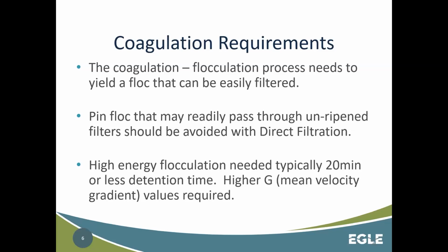So if you remember that slide where a floc particle is much smaller than the pore space between the media grains. So with direct filtration, it's very critical to get that coagulation process correct, so you destabilize the particles so they have the ability to attach to the filter media. So that's one of the key things.